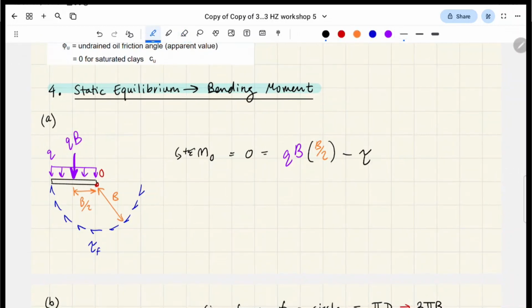When we're analyzing this problem in 2D, you can think of shear strength like a one-dimensional distributed load, similar to what we did there, except it acts that way. Okay, so this is in kilonewtons per meter run. But again, let's not talk about into the page.